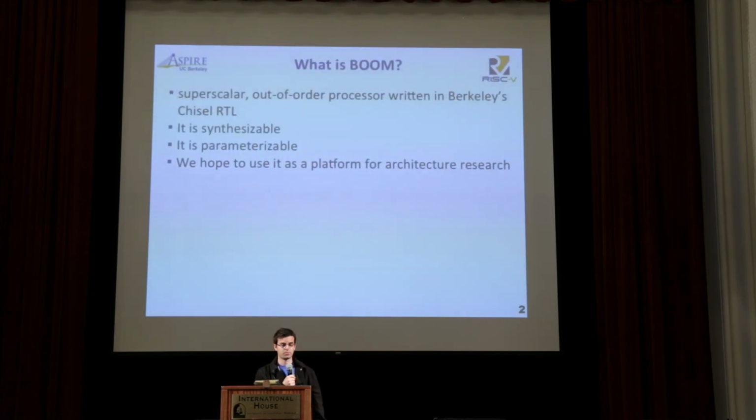Okay, so first of all, what is Boom? Boom is a superscalar out-of-order processor written in our Chisel hardware construction language. Because we wrote it in Chisel, that means it's a synthesizable core. We can put it on an FPGA. We can put this out to a foundry and get a piece of silicon back. Chisel has also helped, as Jonsep just demonstrated, make the design very parameterizable.